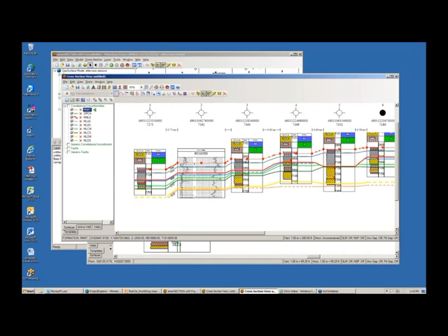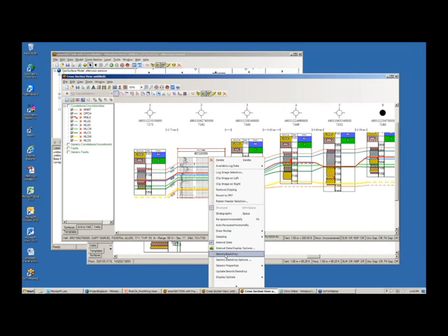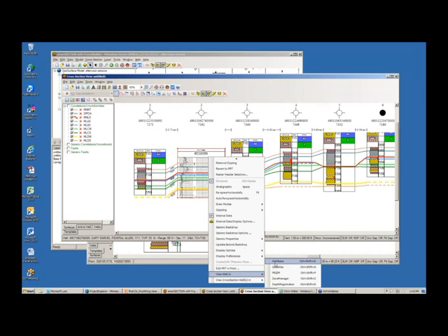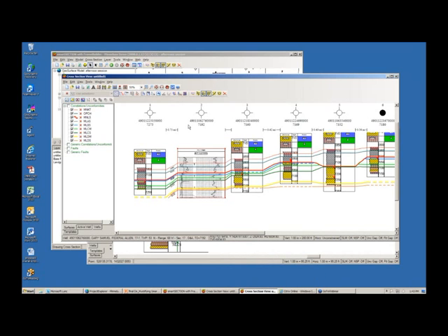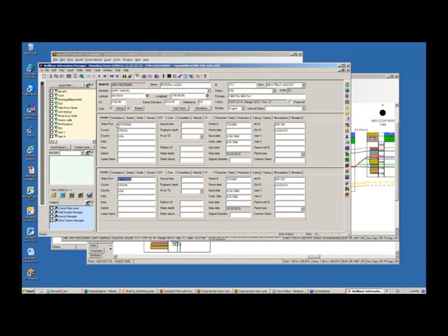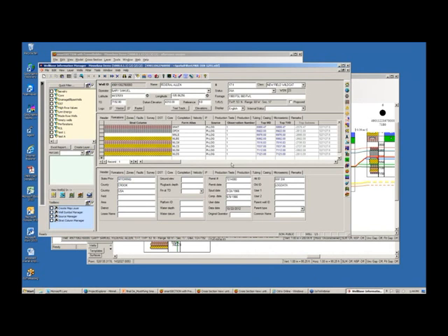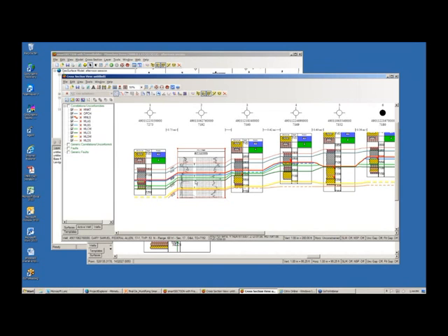When you do pick a formation on a well, these are stored in the WellBase formations data tab. So you will actually be able to instantly see that pick appear in your formations data tab. And just to make a comment on that, you can just select a well, do a right mouse button, and anytime you want, you can view well in WellBase. Your WellBase will open up and you will be able to see in the formations tab your picks. So you have pretty instant access to your database here from smartSECTION, which is a very nice feature.